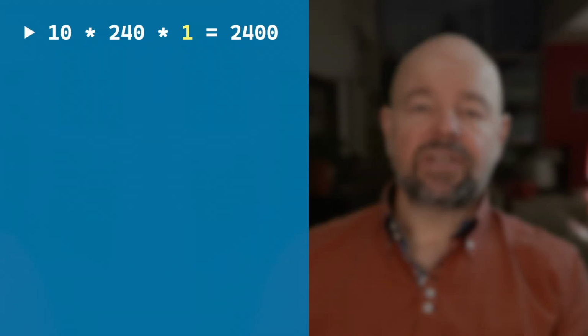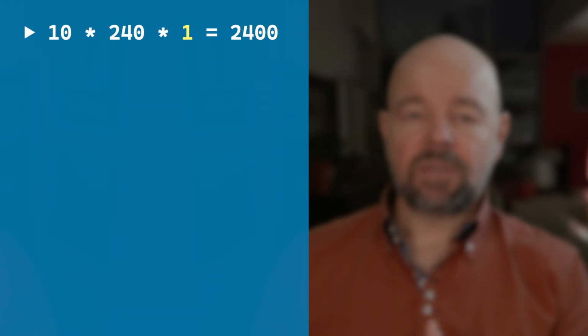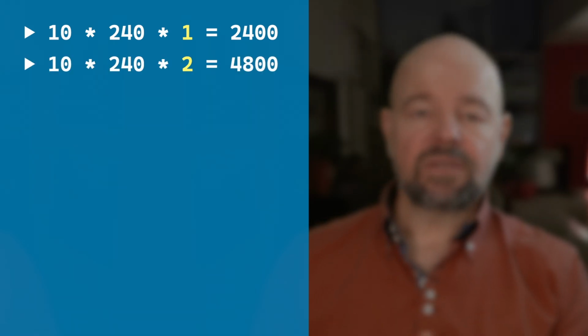The only thing I do with it is I'd like to see whether the car is connected, and I'd like to start or stop charging and set the current. The configured current is per phase. So if I set the current to 10 amperes, for example, for 1 phase, it'll give 2.4 kilowatts, for 2 phases, 4.8 kilowatts, and for 3 phases, 7.2 kilowatts. So the charging power is a combination of the number of phases and the current.